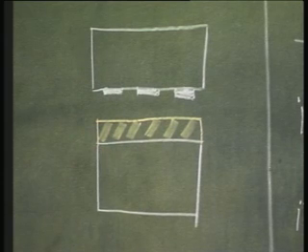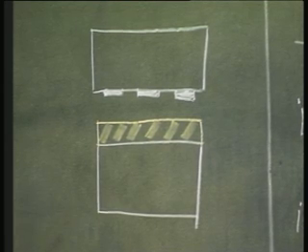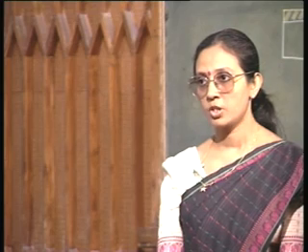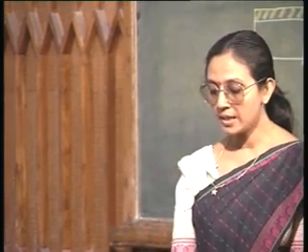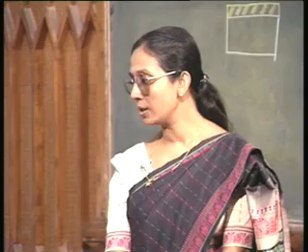Now you allow the radiation to fall onto the wafer through the mask. Only those regions of the mask which are transparent to the radiation allow the radiation to fall on the semiconductor. Now, I told you that the resist is radiation sensitive. So, only those portions which are exposed to the radiation, their properties are going to change. In some cases, the exposed region might get softened, easier to remove. In some cases, the exposed region might get hardened, difficult to remove, depending on the type of resist I have.